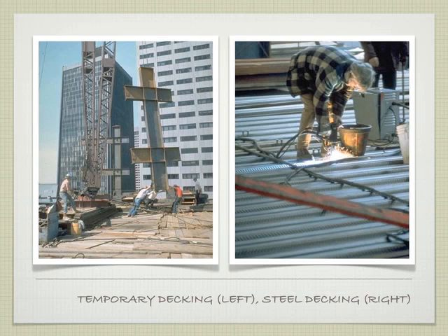Notice that there are a bunch of these little ribs included in the steel decking, right? If you feel these carefully, the ribs exist. I don't know whether you notice those. Maybe if I can turn it in the right light, you can kind of see those depressions. Those ribs and depressions allow the concrete to more carefully bond with the decking itself. So they tie together. It's like the ribs in rebar. Same concept. We're trying to tie those together.